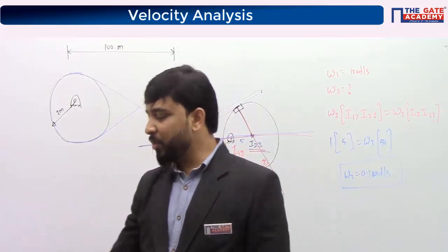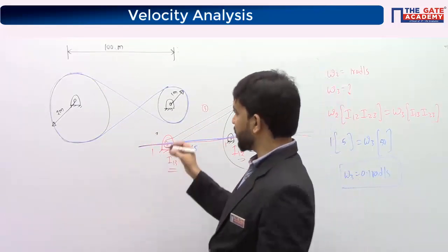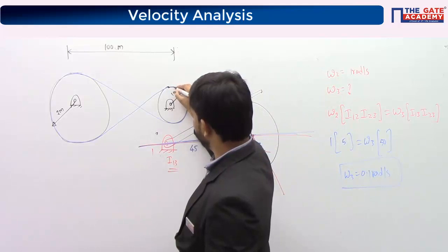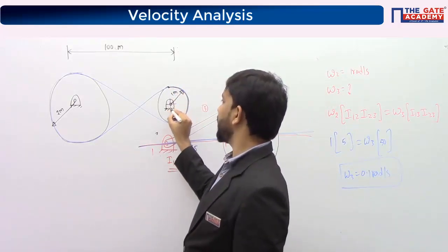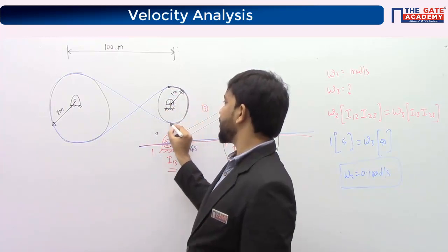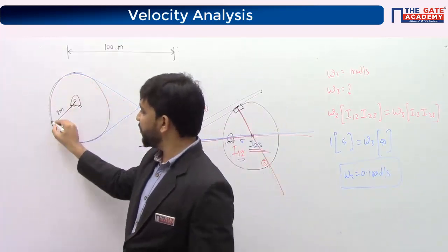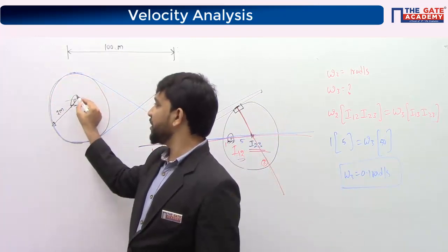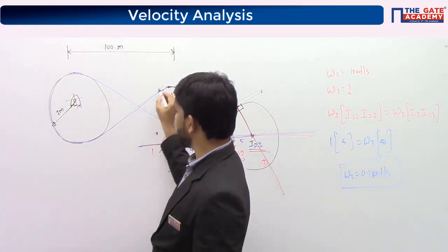If it is a flexible body, the body moves in different fashions, okay. If I take this portion of the belt, it is rotating about this center. If you ask me where the instantaneous center is, this is the instantaneous center, because this portion of the belt is sticking to the pulley. Whereas this portion of the belt is moving along a straight line, yes or no?